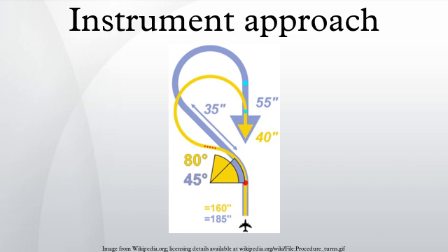If runways are less than 3,000 feet apart but at least 750 feet apart, simultaneous offset instrument approaches may be used. The procedure is similar to that described above, except that one aircraft flies the ILS PRM approach, and the other flies an offset LDA PRM approach at an angle to the runway centerline. The aircraft flying the LDA PRM approach with glide path is positioned to be behind the ILS PRM aircraft, and must have the ILS PRM aircraft in sight before beginning a visual segment to the approach at or before the missed approach point. During the visual segment, the LDA PRM aircraft must keep the ILS PRM aircraft in sight as it aligns with the centerline of the runway.